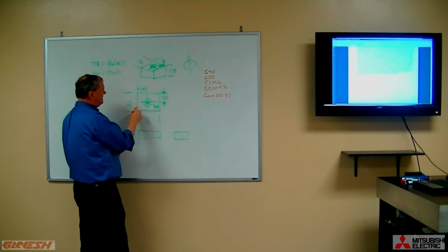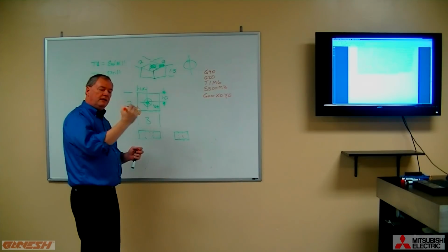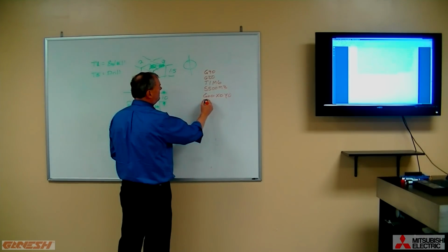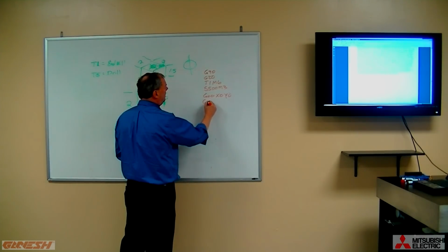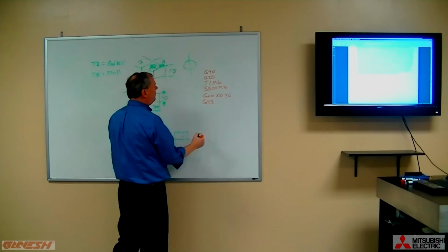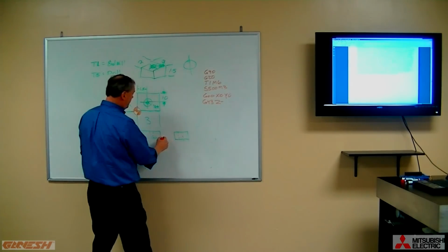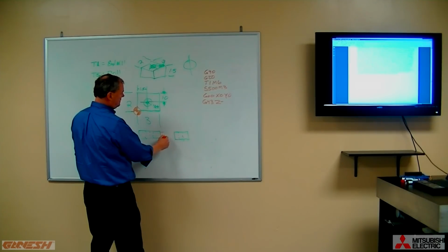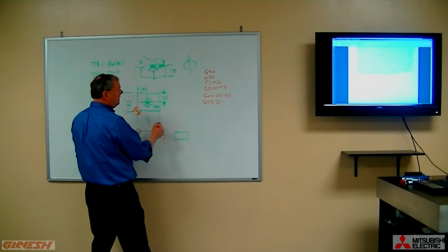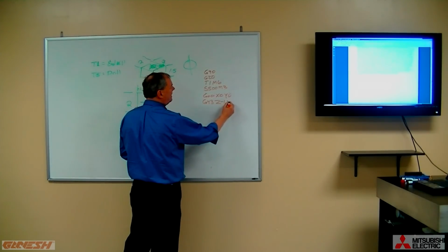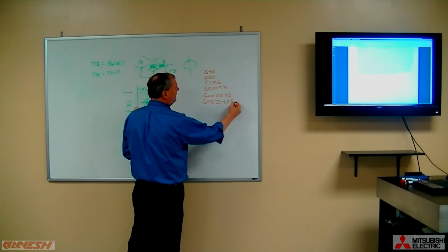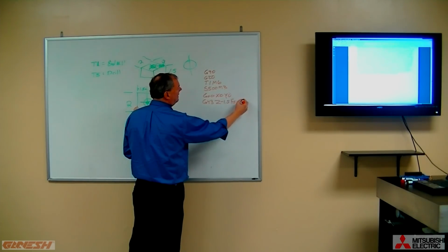So now our tool is sitting up here. Now we want to kick in the offset to activate tool number 1. If you remember, we're going to use G43, Z minus, and if this part is 1.5 inches thick and the top surface is Z0, Z minus 1.5, and then give it a feed rate of 5.0, but we can also then say H1.